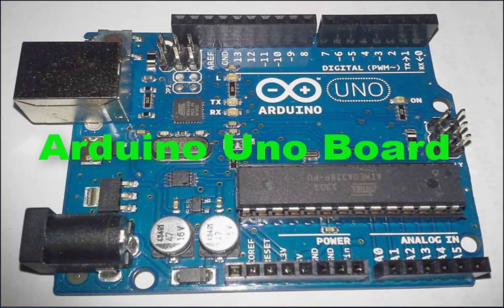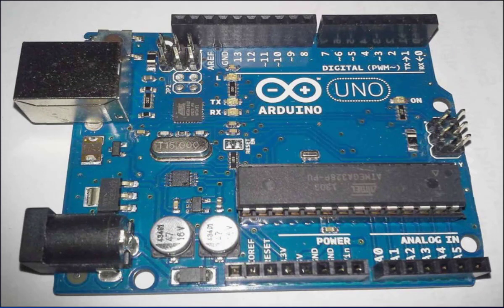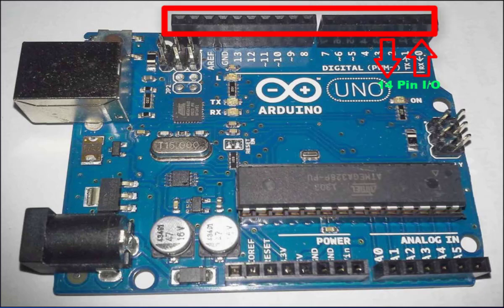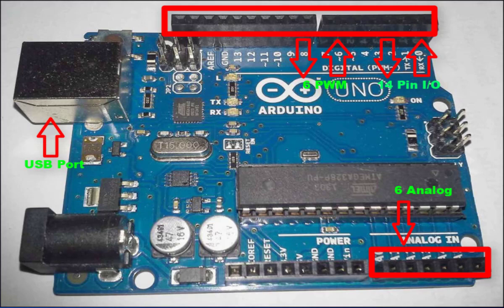The Arduino Uno. The workhorse of the Arduino family is the Uno. It's the most popular Arduino unit and provides the basic functionality of the ATmega AVR microcontroller within the standard Arduino footprint. It uses an ATmega328 microcontroller, which provides 14 digital I/O interfaces, 6 analog input interfaces, and 6 pulse width modulation or PWM interfaces for controlling motors. The Uno circuitry also contains a USB interface for communicating with workstations as a serial communications device, a separate power jack so that you can power the Arduino Uno without plugging it into a workstation, and a reset button to restart the program running on the Arduino.